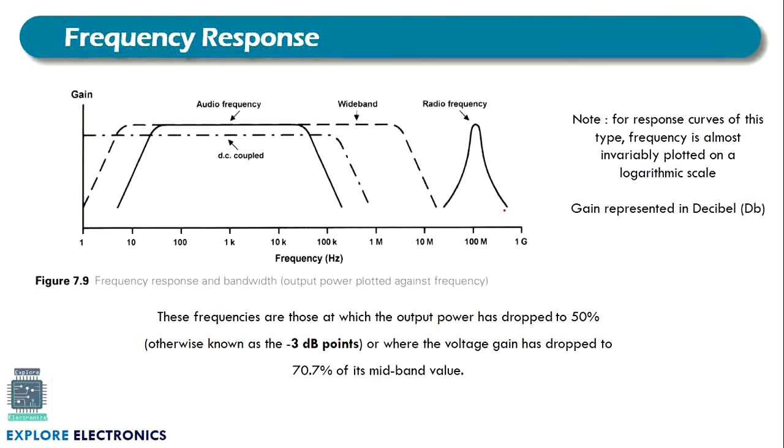What it is giving as information is that on the x-axis we have frequency and on the y-axis we have gain. For the radio frequency amplifier, we are going to get gain only at these frequencies. This is the set of frequencies where the radio frequency amplifier is going to amplify. Here we are going to get the maximum gain. As the frequency becomes lower, it goes out of the radio frequency range, and that amplifier is not going to amplify. By looking at the frequency response of any amplifier, we can see clearly from which frequency to which frequency the amplifier is going to amplify.